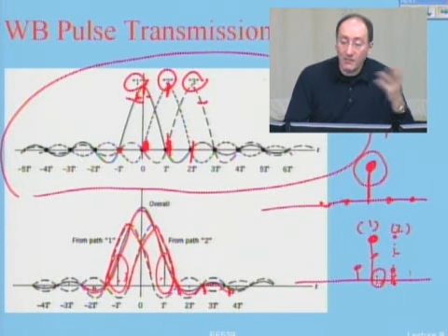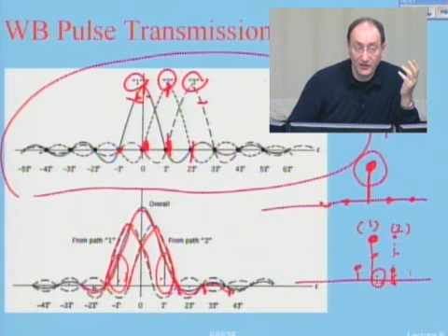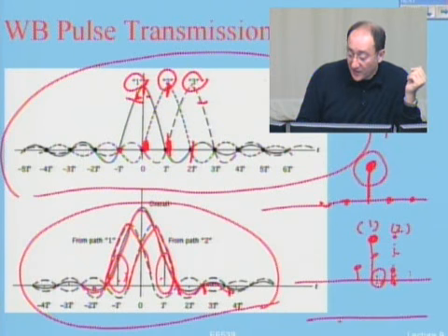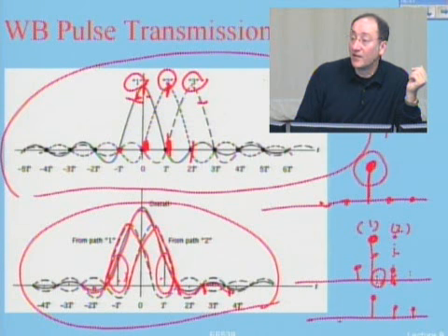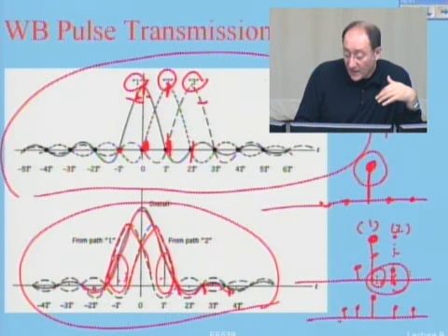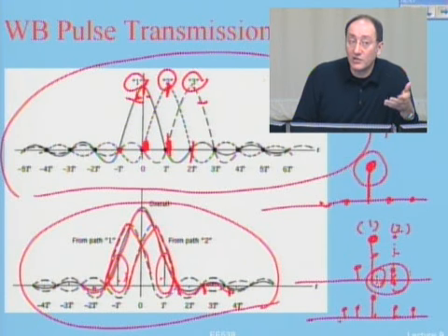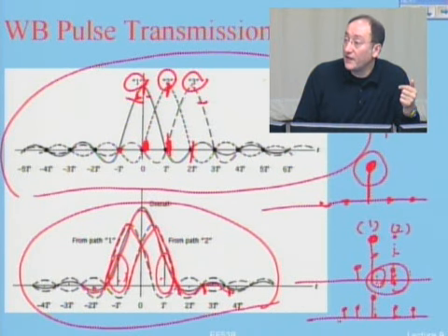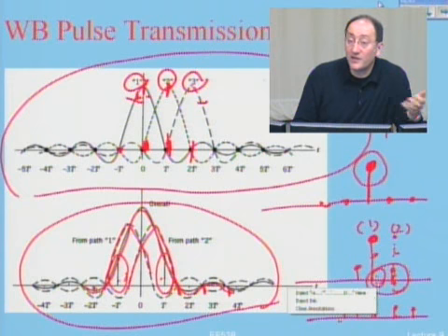Now, if I'm somehow smart enough to measure the impulse response in a multipath environment, I have several paths. I have an impulse response like this, for example. If I'm smart and avoid this intersymbol interference, each of these paths is like a source of diversity, actually, because they are going to fade independently from one another.